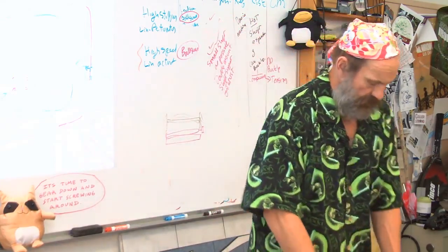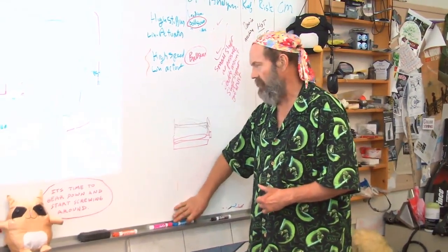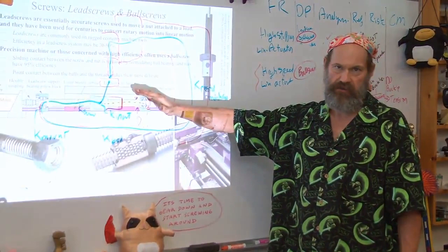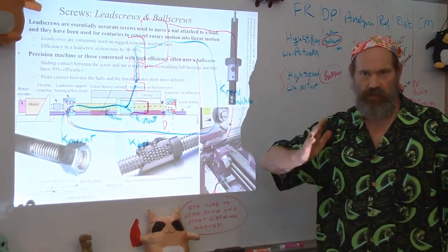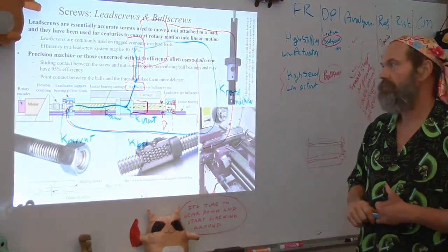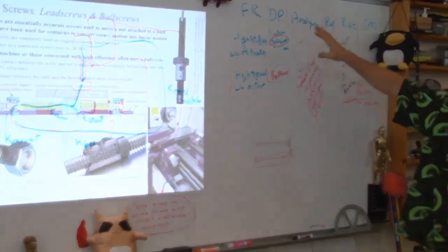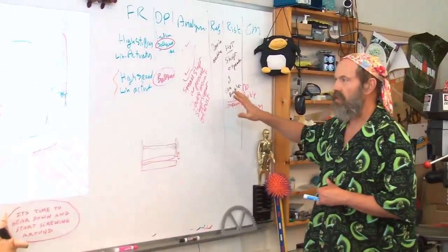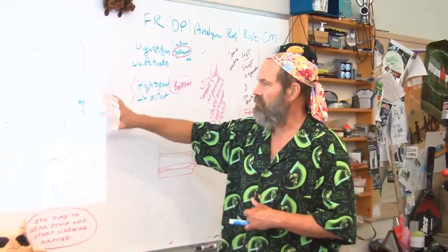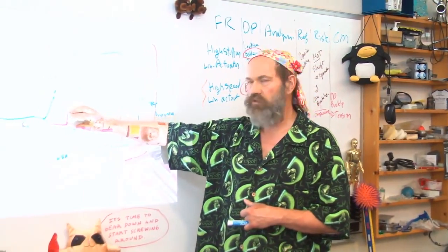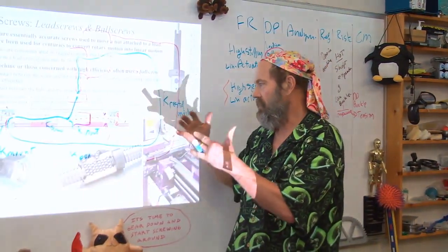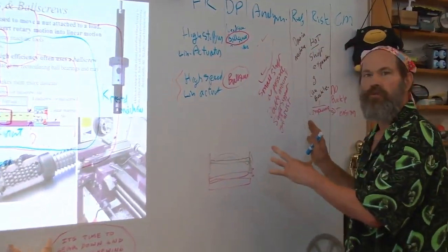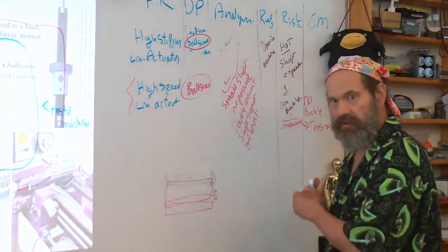I can even go so far to remember that there are special types of bearings called ball screw support bearings that have very special angles between the balls and the races, such that they take very high thrust loads very, very efficiently. So you see how we've gone this full circle, starting way back in topic 1, all the way through how we apply these thinkings from the fundamental principles, all the way through if you have a screw shaft, this machine element, how do you use it? Think about it in the context of a machine and the types of analysis you're going to need to do to move forward.